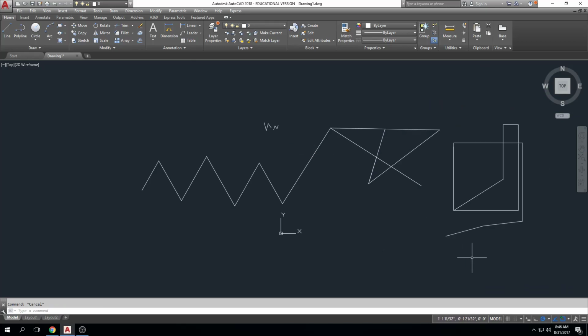So we'll stop there with the object snaps. There's one more drawing aid we'll talk about probably next time, but we'll stop there with all of our object snaps. But just remember, we have our ortho. We're going to F8, turn that on and off as we're drawing lines because we want straight lines in AutoCAD. We have our object snaps, midpoint, endpoint, perpendicular, nearest, right? Those help us achieve drawing lines on certain points or certain places on lines.